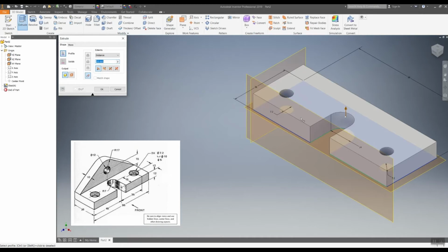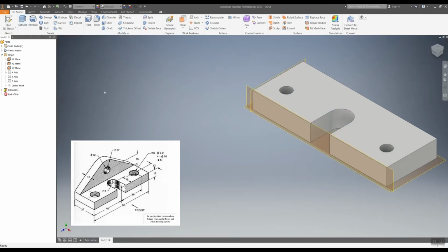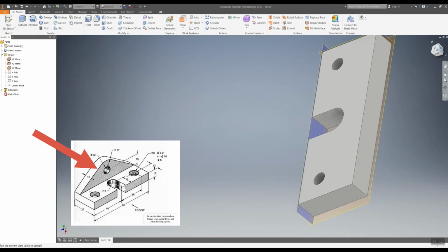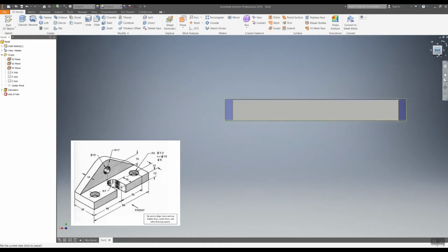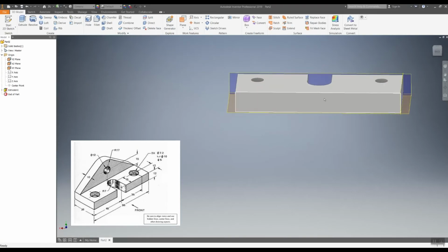So this whole thing is 12 high, so I'm just going to make it 12 millimeters high. That completes the first part of my project. Second part here I have to do on this back side. So I'm going to rotate this around here, poorly as usual. And I want to draw on this back side here, because I want to extrude this part up.